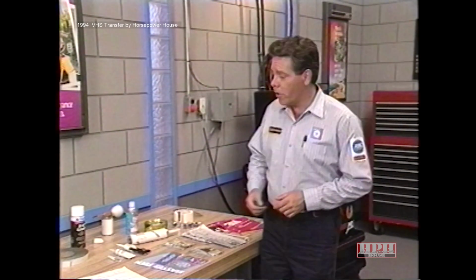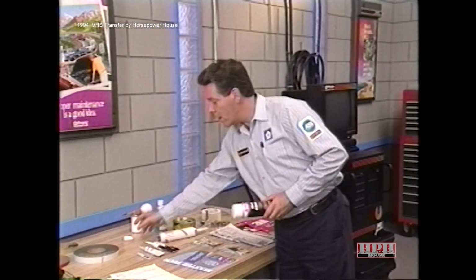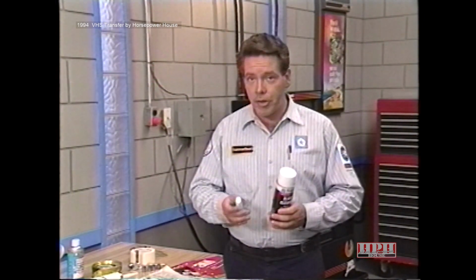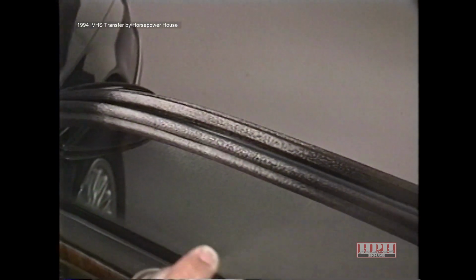When a deck lid or door weather strip seems to be at fault, you may want to use the foamy window cleaner test or the chalk test. These are both excellent methods for locating large seal leaks. And with the exception of the materials used, the procedures are identical. To begin, open the deck lid or door where the leak is suspected and apply an even amount of foamy window cleaner around the entire perimeter of the suspect weather strip.